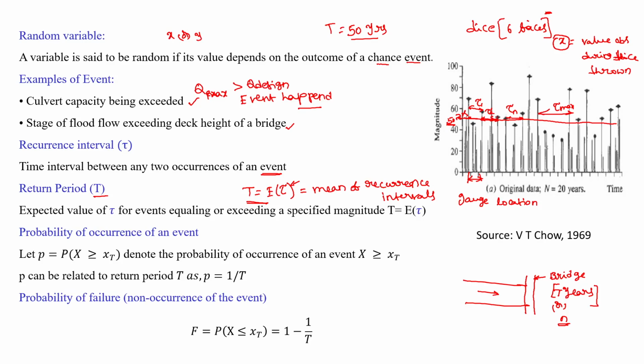And one more confusion is, let's say in 1947 this event happened, let's say a Q event happened. So when we say this is a 50-year event, then people tend to imagine that 1947 plus 50, maybe 1997, after 50 years only there would be another event. This is wrong. This is also a wrong perception. See, if you observe all these weather bulletins, they say that we observed a 100-year precipitation event or 200-year precipitation event, especially if you look at the 2018 Kerala floods.